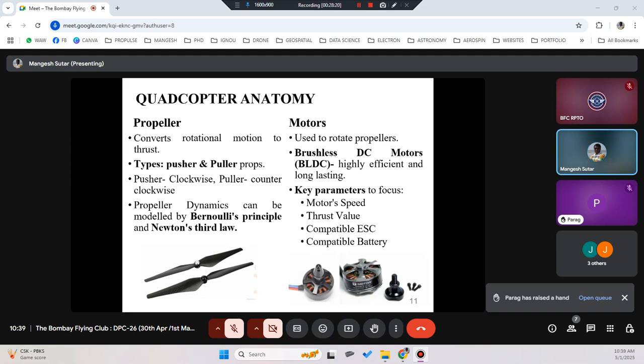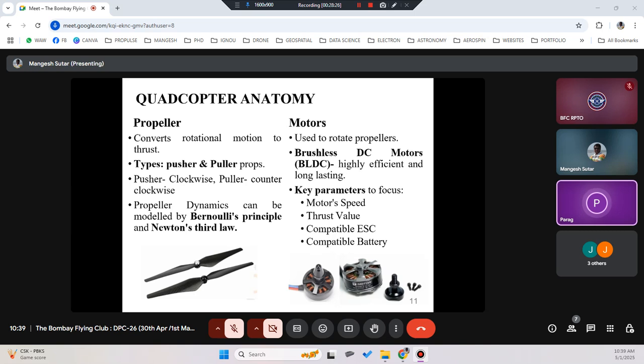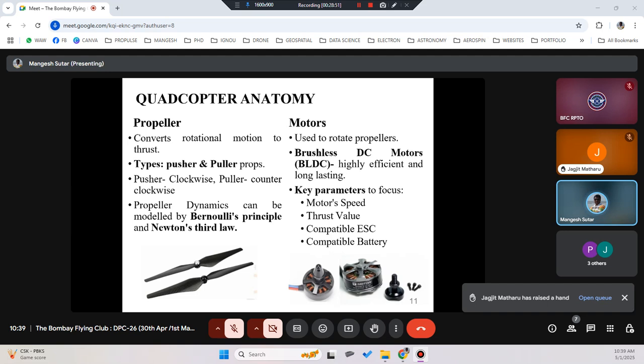Yes, Parag, you have a question? I just wanted to check about this. When you say it is like a thumb rule to be on the safe side, whatever is the half would be the take-up capacity of that particular drone? Correct, it is a standard rule. That is what is followed worldwide, whenever we design drones with BLDC motors. For internal combustion, it is altogether a different concept. It goes as per a different principle, because internal combustion is mostly used for fixed wing aeroplanes. Yeah, Jagjit.